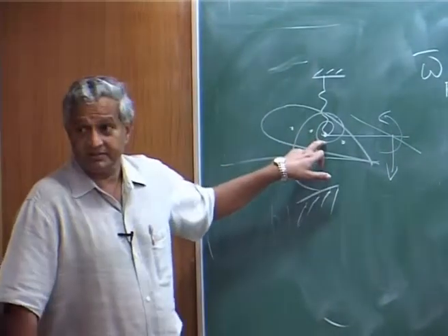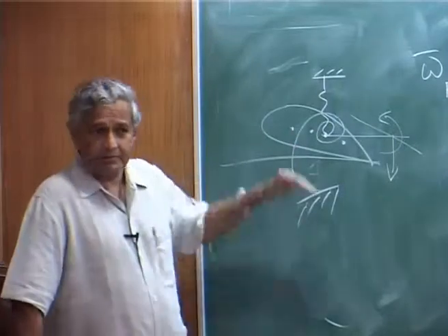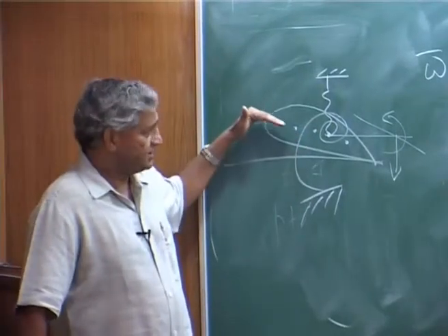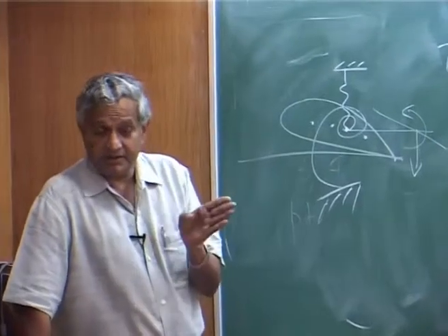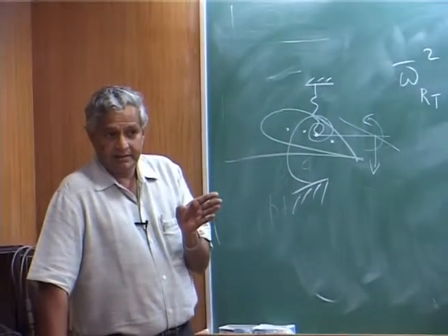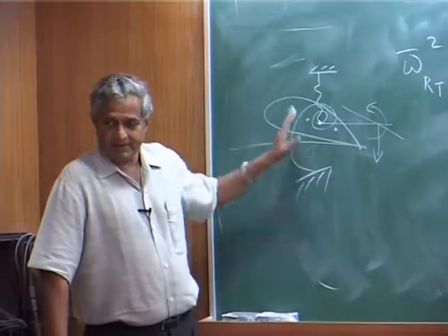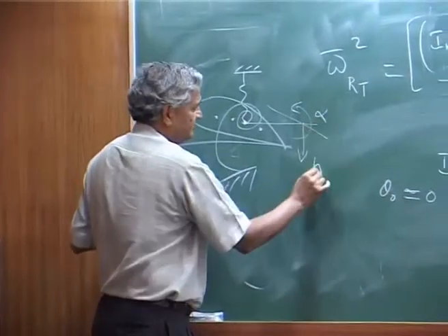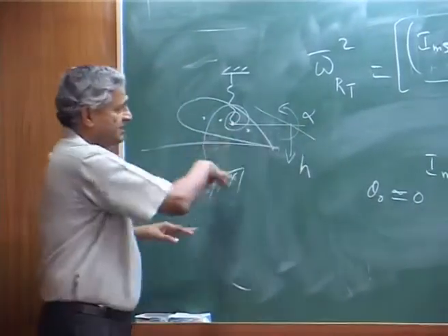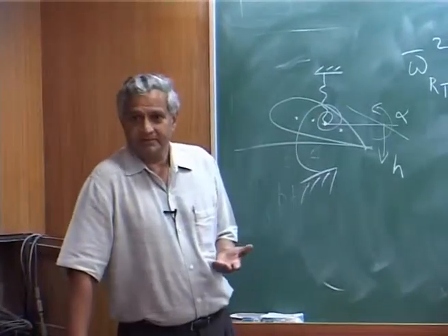This is the elastic axis. So this is a 2D airfoil. Now the theory associated with the 2D is Theodorsen's theory in the subsonic, incompressible regime, and that theory takes care of both h and alpha. h is the heaving motion, alpha is the pitching motion.